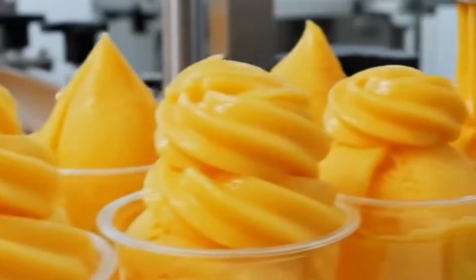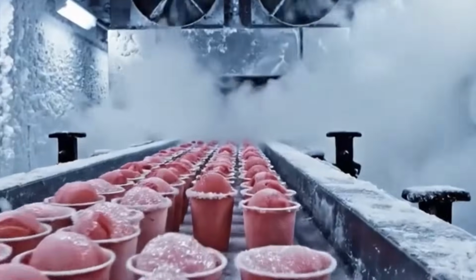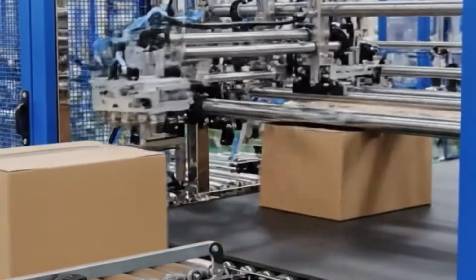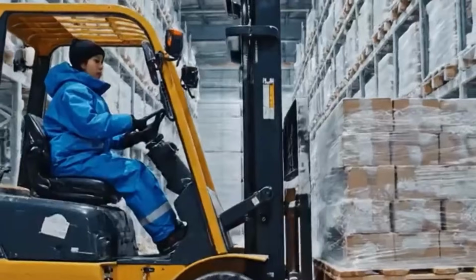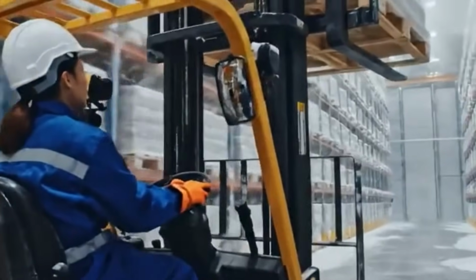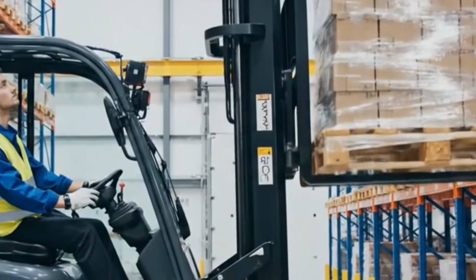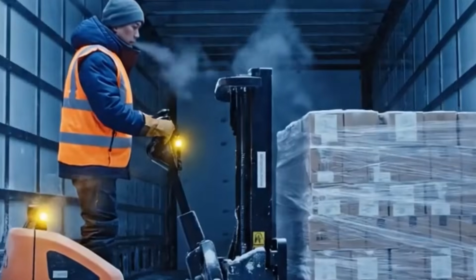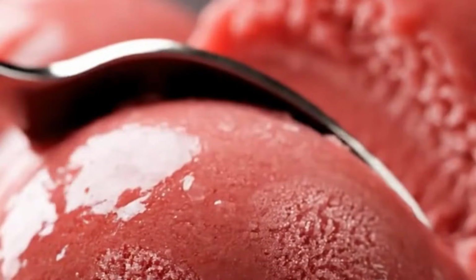Cartons are then routed to the palletizer. Layers of cartons are stacked according to a programmed pattern to optimize pallet stability and maximize transport efficiency. Stretch wrapping machines encase each pallet in multi-layered film with preset tension profiles to secure the load during transport. Pallets are labeled with SSCC codes and sent to deep freeze storage, where ambient temperature is maintained between -25 and -30 degrees C. Storage location is recorded in a warehouse management system using RFID or barcode scanning.